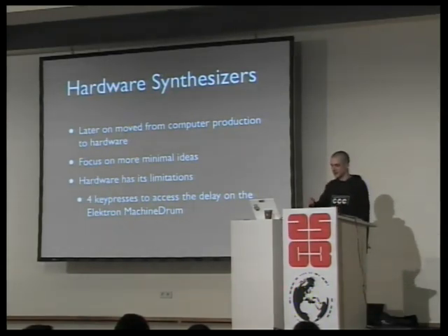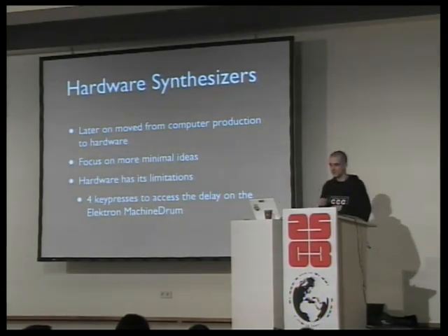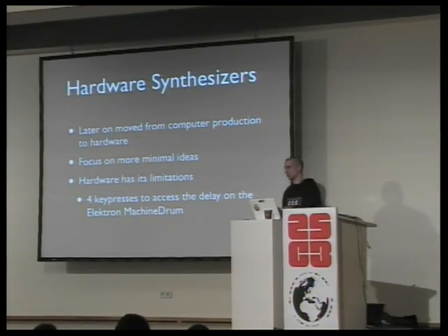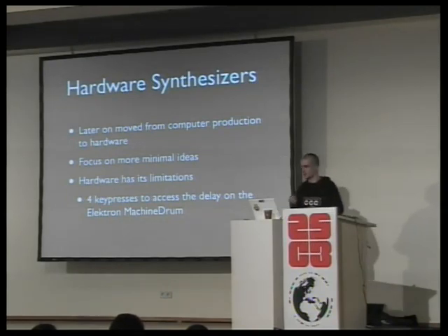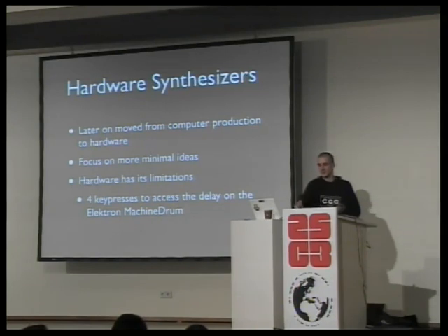So for example, on this machine I have an effect called a delay, which just repeats sounds at specific intervals. And to access the parameters for this delay, you have to enter menus and press a lot of buttons. So it's not really something you would like to use live and change the settings on the delay when you're in a club. So I downloaded the manual for this machine, and when I was looking for manufacturer-specific messages to change the way the delay is set, I found out that you can actually set the delay settings using a MIDI message which is sent over this cable.